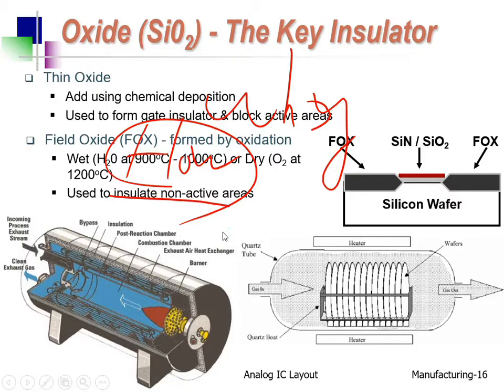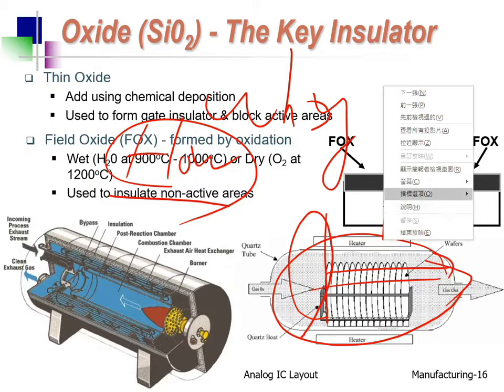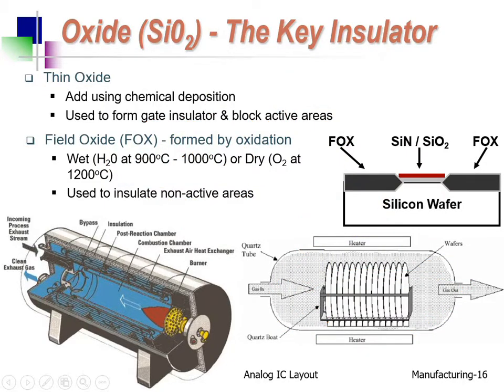Okay? And this is a very good example for systematic mismatch explanation. It happens all the same. The oxidation thickness from here to there, from the input to the output, from thicker to thinner. Okay? And that is also a very good way to tell you about the so-called wafer to wafer mismatch.